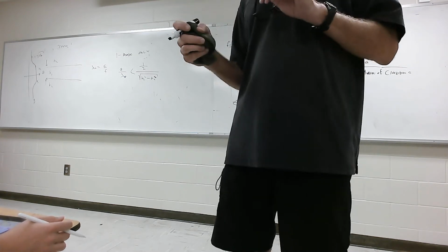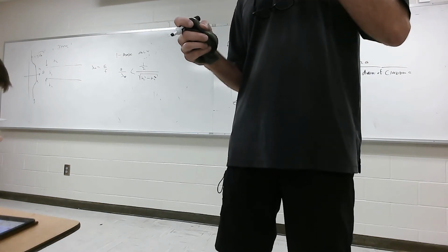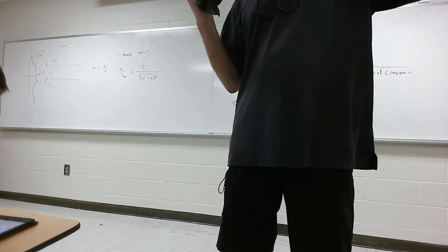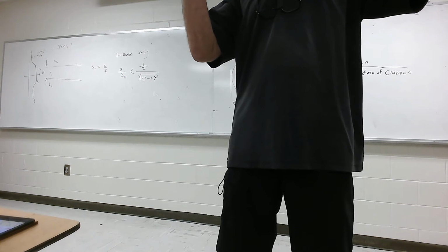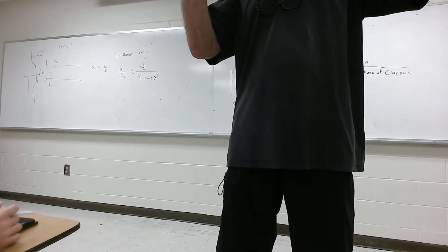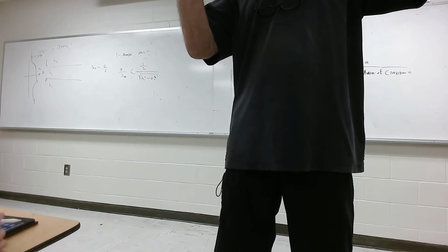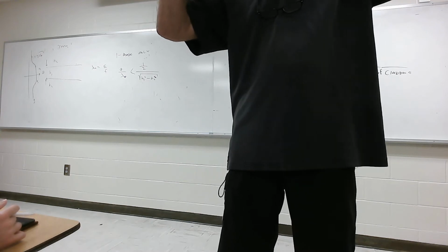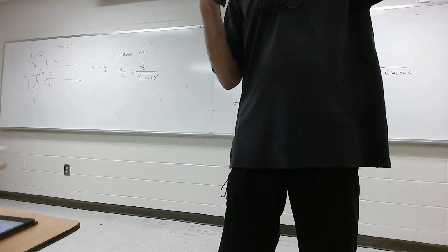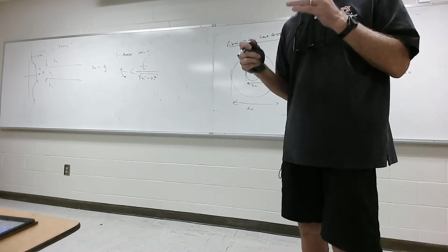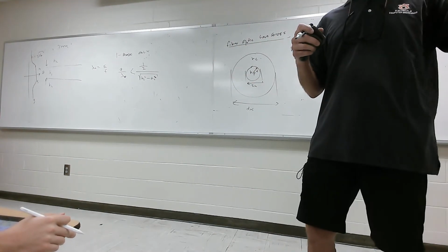We ran fiber backbones. I'm going to put up a video. It's really good. It shows actually a fiber optic tube. When you go beyond a certain critical bend, all of a sudden it doesn't work. Then you get terrible reflections. Fiber tubes and stuff like this have what's called a minimal radius of curvature that you can actually bend these fibers at before they start really spraying signal all over the place.